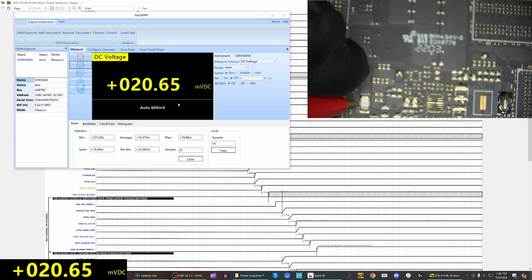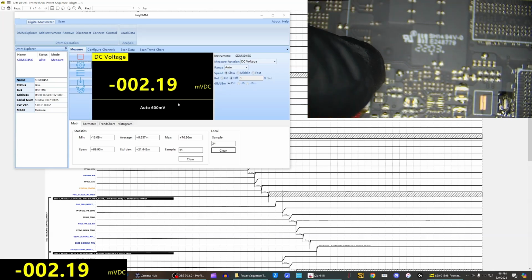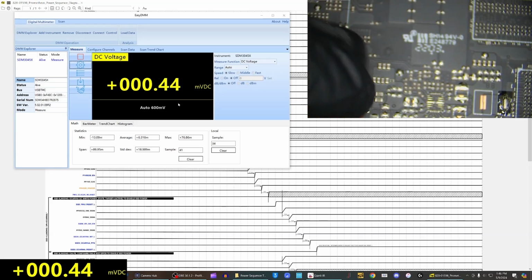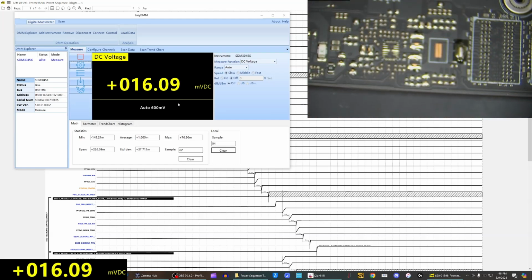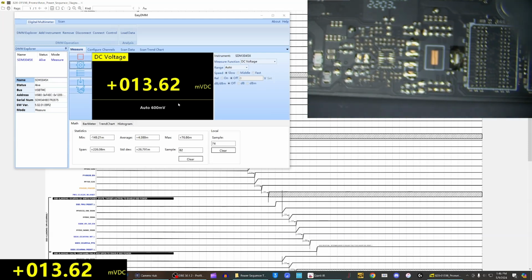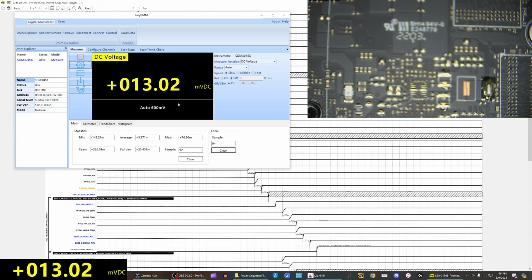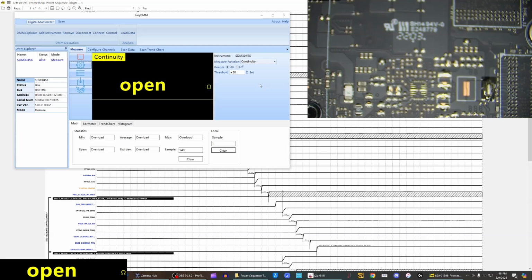Okay, right. So I just saw a stable-ish low voltage on this fuse, and I'm like, oh, this is like a fuse for main or something, like the PP bus fuse for this Razer. It's basically how I'm thinking about it. Then I take out power and check: do we have a short on this? We do.